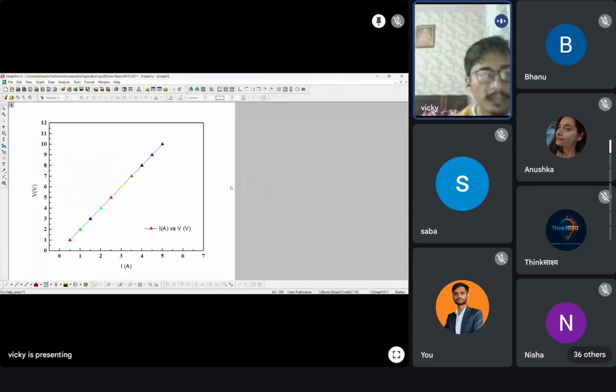After doing all the labeling and things, you can move this particular graph. For that purpose, you have to save it. For saving, you go to File and choose Save Project As. Here's the option where you can put a file name. Let's say I put Ohm's law plot. We have different options to save it, but it's usually saved as a project.